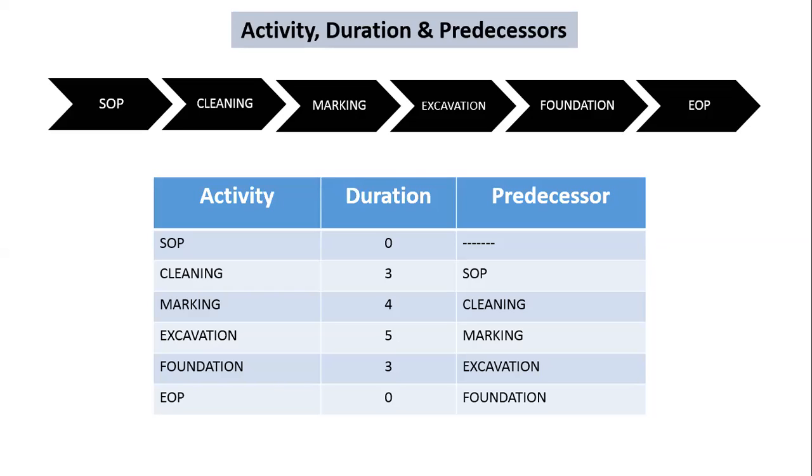Apart from design and planning, we will start cleaning of the site. Then we will go for marking. Then we will go for excavation. After that, we need to go for PCC and the structures, beams, and all. For this, we will get foundation. It's an activity that I have mentioned for this example. This is a small project that we are having.